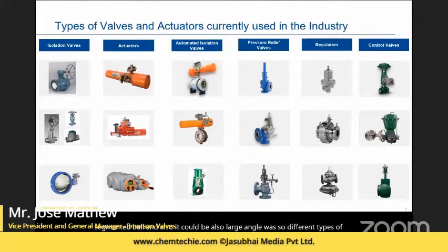And then you could have a valve which probably costs just a couple of $100. The control valve at the bottom right, those are angle valves, special control valves, typically used for anti-surge applications in special materials and things like that. Those could even cost more than $1 million. So it's a wide range in terms of price, and they are used for different applications.